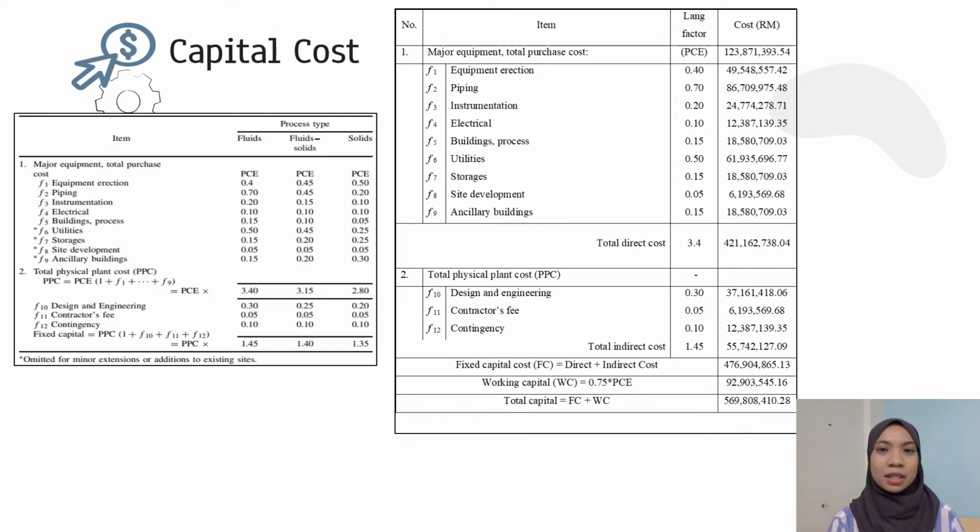Capital cost estimation is used to estimate capital and operating costs for a chemical processing plant. Lang factors are typically considered when calculating capital costs. While there are general Lang factors, which are for solids, fluid, and also mixed processes, it is recommended that the factors be considered individually. Since our industry mainly processes fluid, values for fluid are taken.